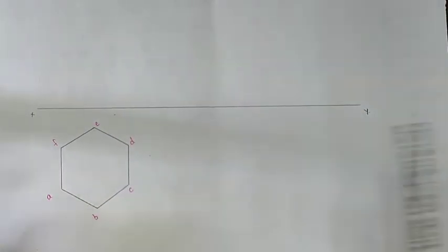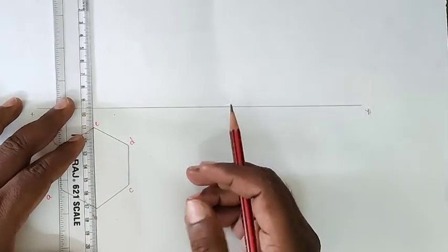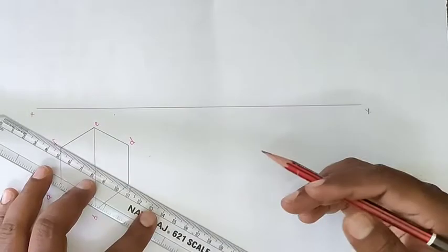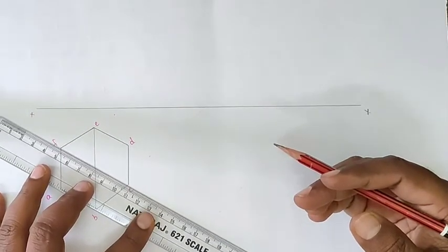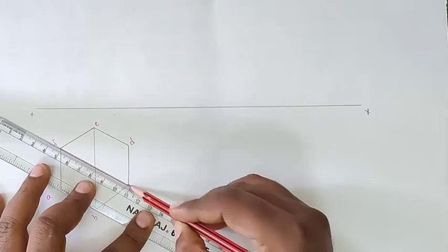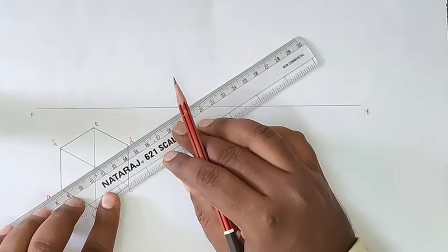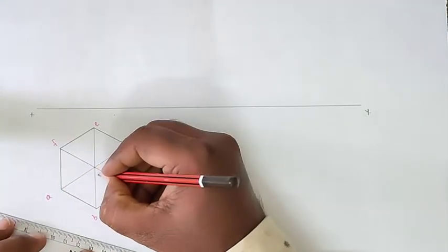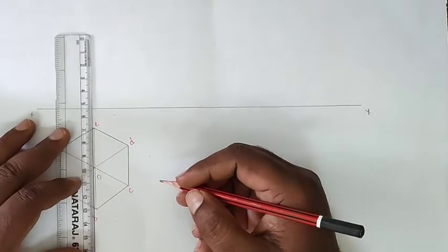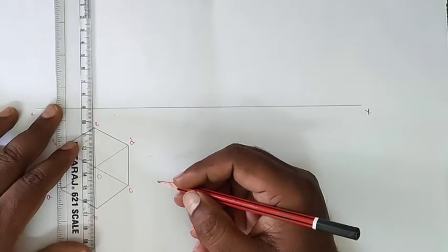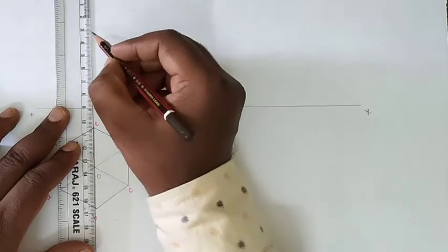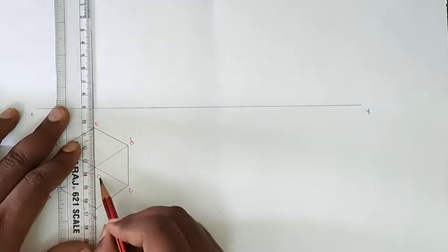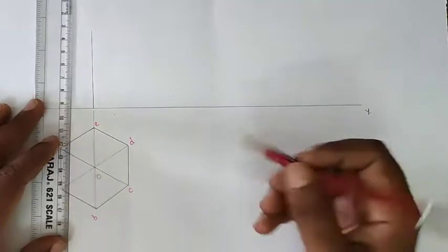After drawing the pyramid, we also draw the inner edges thick. For locating the center, we draw the diagonals joining the opposite corners, all the diagonals like this. We will get the center O. Through the center we will draw the axis height, which should be 60 here. So the axis is here; make it thick, because the center is passing through the point B.